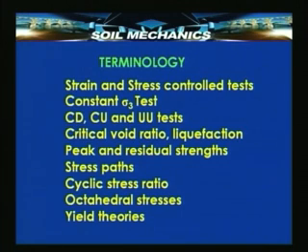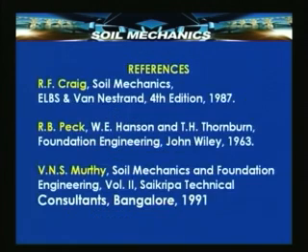We have used a number of terminology. You are advised to go through this complete list of terminology and understand their real meaning and significance in practice. The terminology are strain and stress control tests, constant sigma 3 test, CD, CU and UU tests, critical void ratio and liquefaction, peak and residual strengths, stress paths, cyclic stress ratio, octahedral stresses and yield theories.